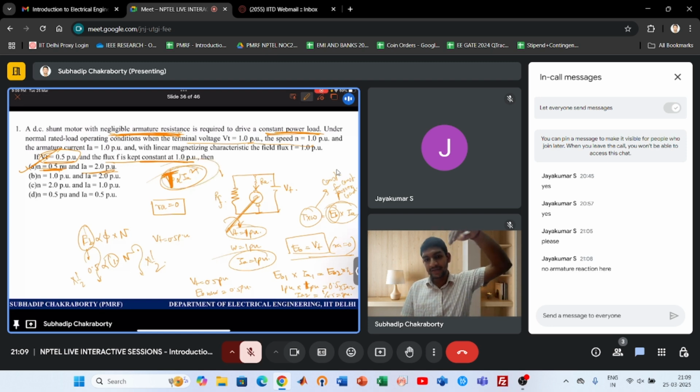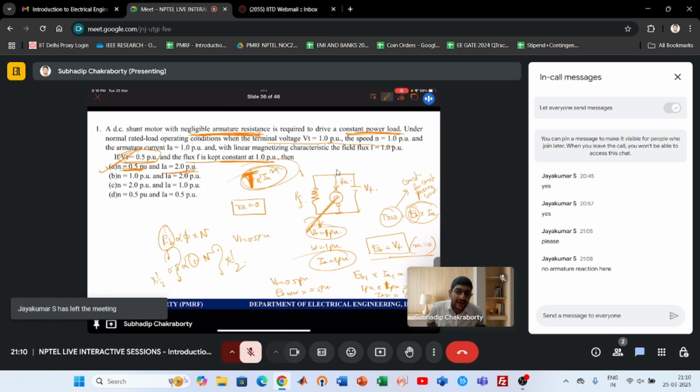Up to a point it will be parabolic for a series motor, the torque with increasing current, then it will be flat, varying linearly with current because flux will be saturating, right? And obviously there will be some armature reaction also. So the flux will tend to reduce or stay at a constant point. While solving problems, if nothing is significantly mentioned, such as that due to armature reaction the flux is reduced, like for example to 0.7, so the flux becomes 70%, then you can assume that in the new case. But in the old case and the new case, if nothing is mentioned,